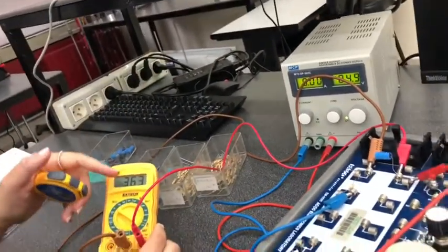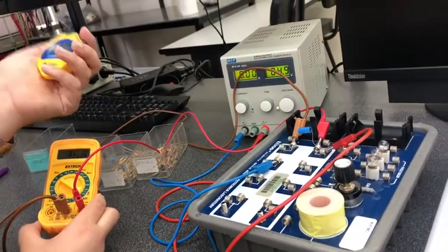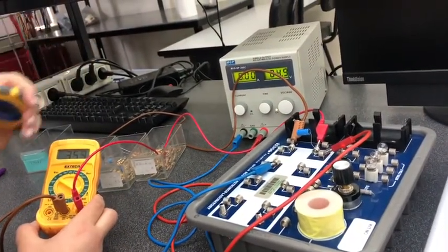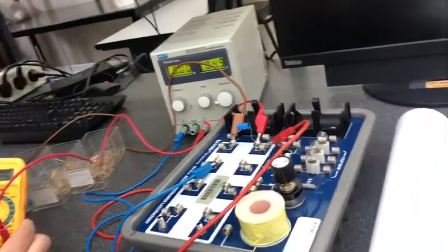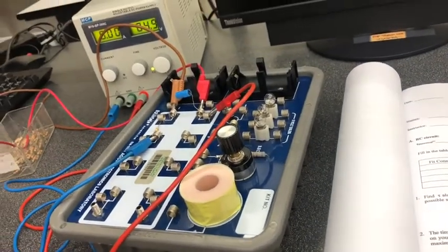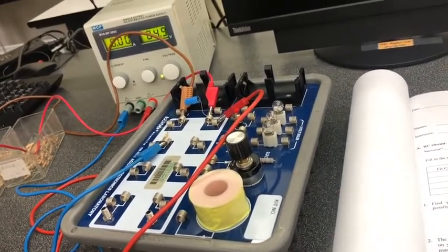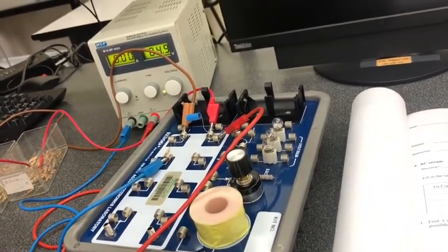Now, a source of error is synchronizing the voltmeter with your experimental timer. If you want to be more accurate, you can repeat it many times, or you can wait until you get to 5 volts, which means you are waiting to reach 5 tau.